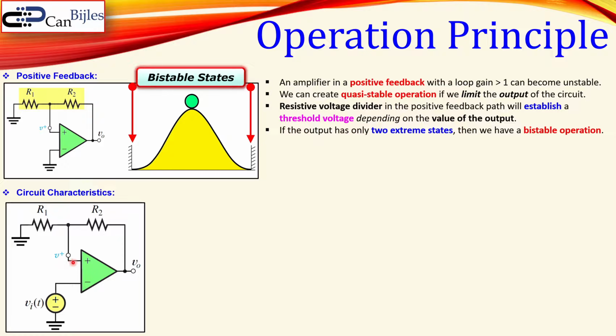In the reverse case, that means inverting input voltage larger than the non-inverting input, then this goes to the smallest value, the most negative output voltage. But it can be that, of course, the op-amp in practical cases consumes some voltage, so that will be less than what you supply for your operational amplifier.